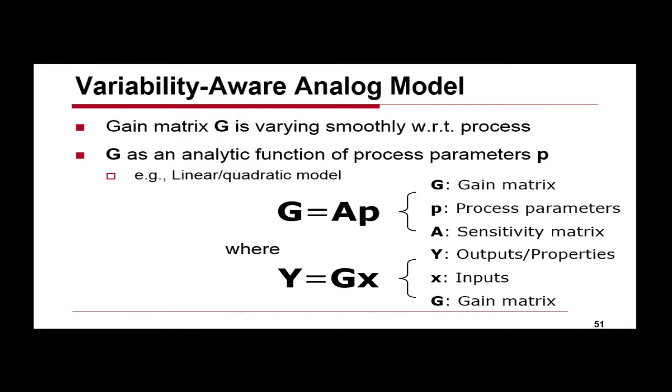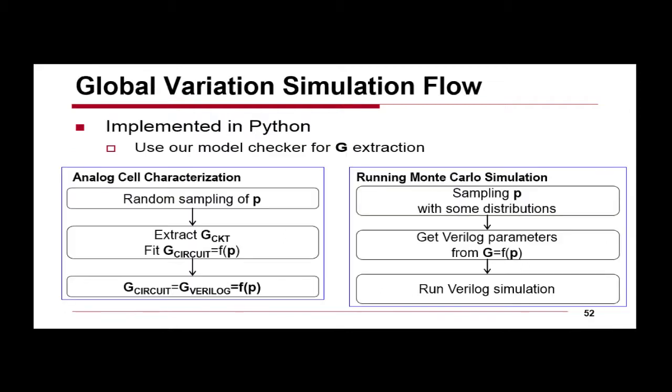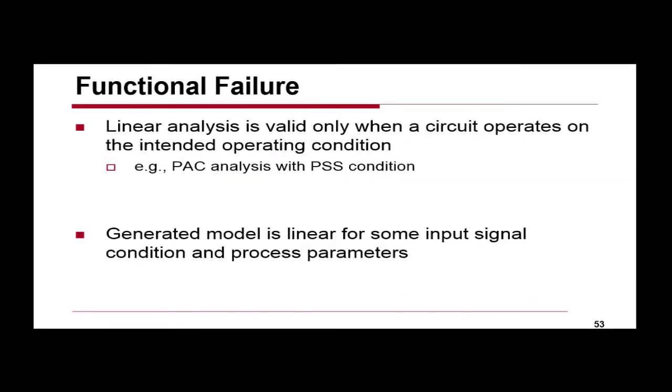So at the system level, we can essentially do the Monte Carlo sims that you would like to do. And the answer quickly is yes, you can do that. And I'm going to skip that. The interesting thing is that there are two ways that parametric variations affect a circuit. The first way is to change the gain or bandwidth of the circuit. But the second way is actually to make the circuit not work.